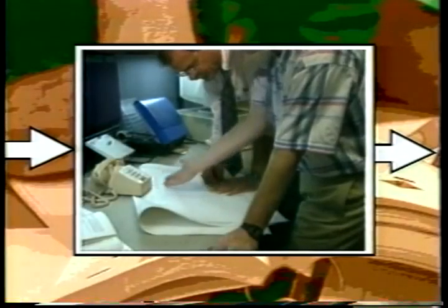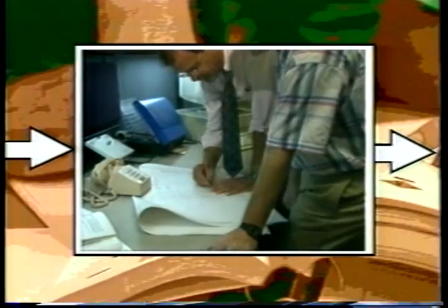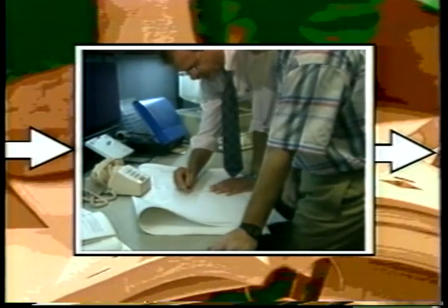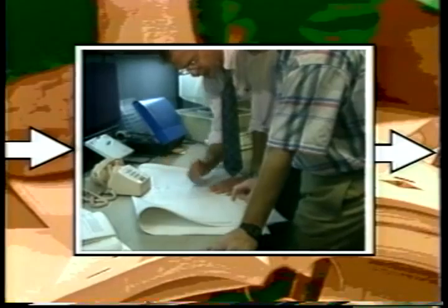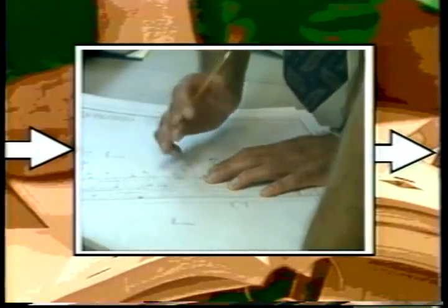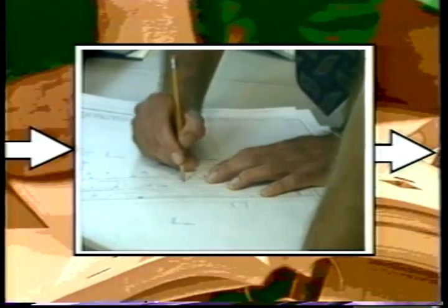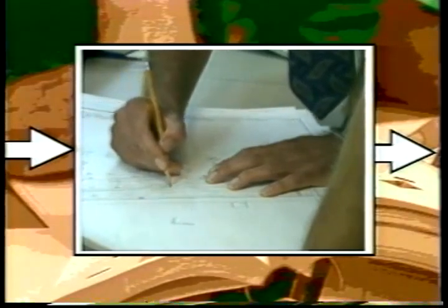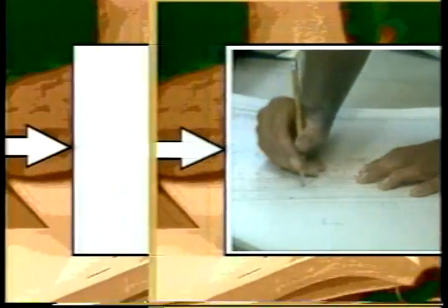With all data assembled, the team can concentrate on the next step, determining the extent of roadway occupancy. It is necessary to determine which lanes or portions of lanes will be closed, as well as how long they will be closed. In short, what is the expected roadway capacity reduction?